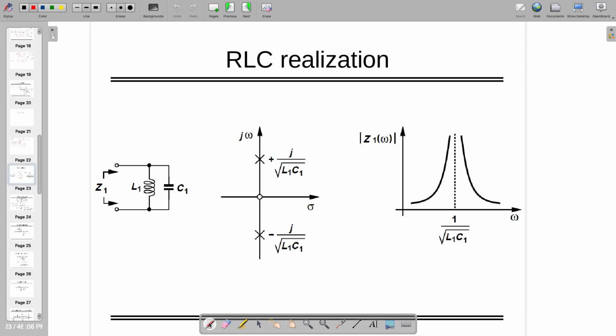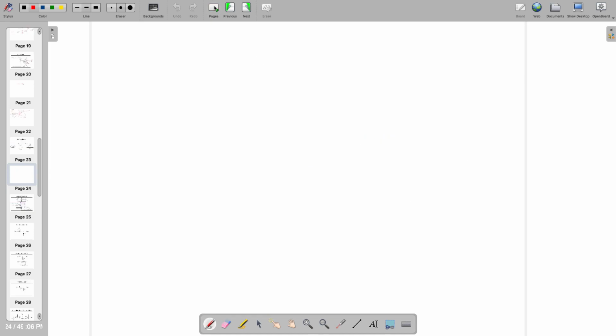Anyway, we were talking about filters, and in filters we learned that there might be first order, second order, or various orders of filter depending on how many elements are there in your system. If those elements are inductors and capacitors, the effective number of inductors and capacitors will tell you the number of poles or the order of the system.